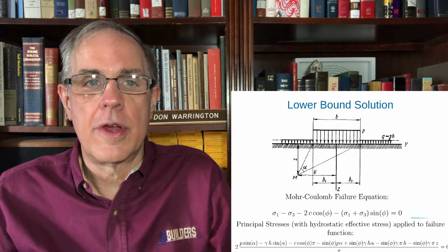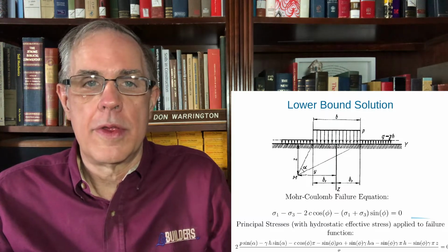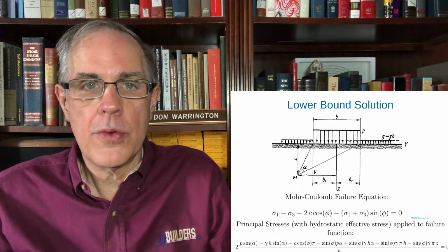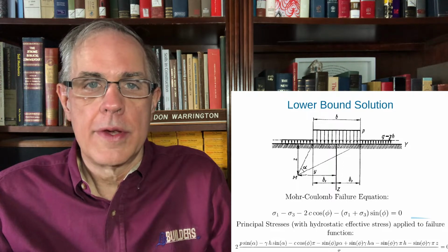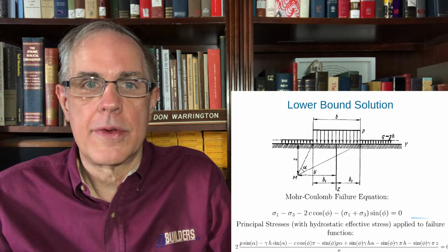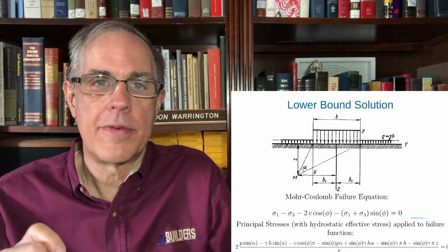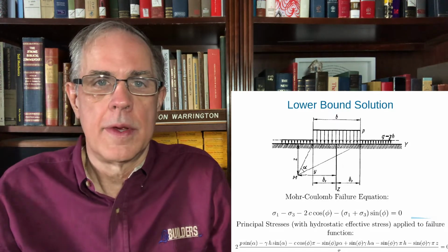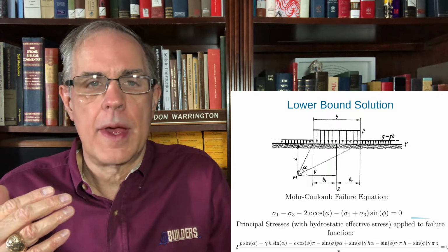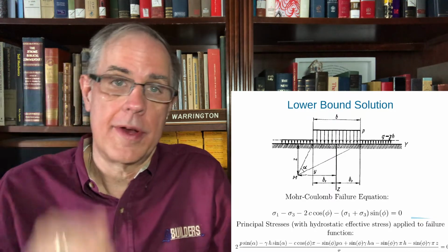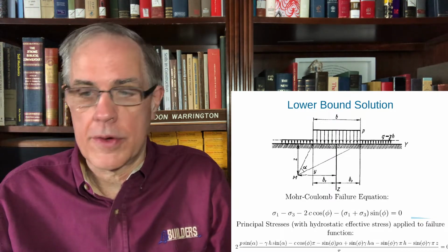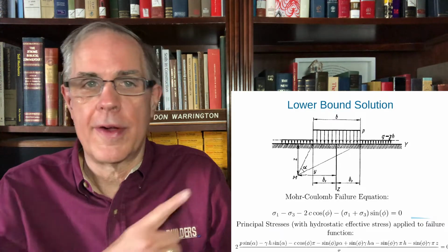That surcharge load is equal to the unit weight of the soil times the depth, in other words the D from the base of the foundation to the ground surface, or gamma, or in this case we call it H.